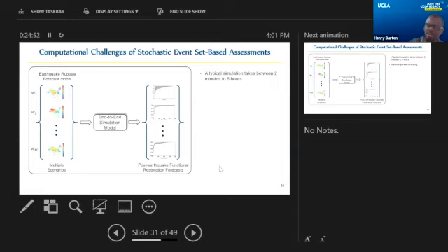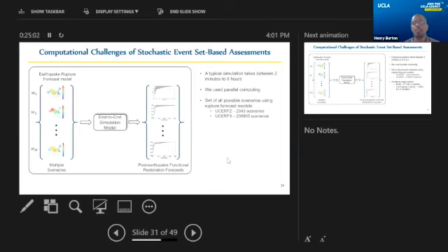So depending on the level of damage and how much is damaged, one single end-to-end simulation can take anywhere from 2 to 6 hours. Now, we did use parallel computing, so that helped a lot. But I mentioned that in this case, we considered the UCERF2 scenario, which only has 2,300 events. Well, the UCERF3 model, which came out within the last 5 years or so, has the number of events increased by a factor of about 100, right? So you can see how the computational expense could scale up significantly.